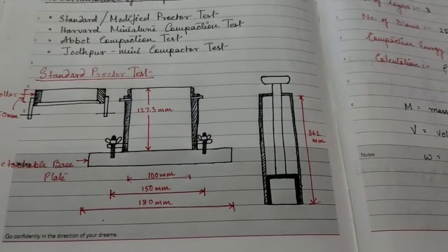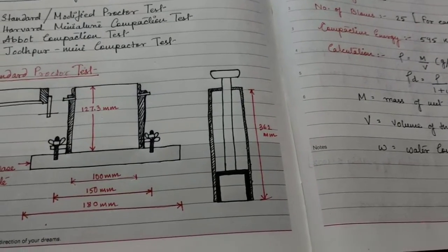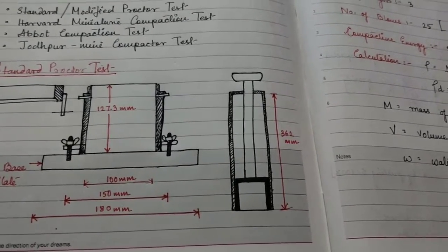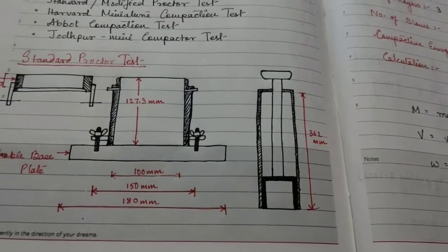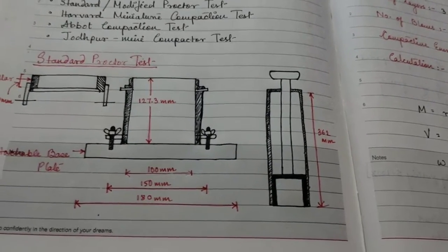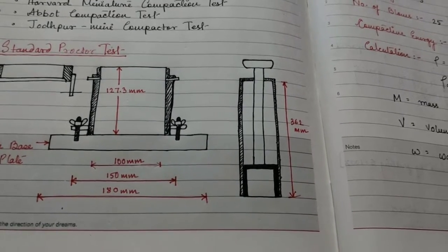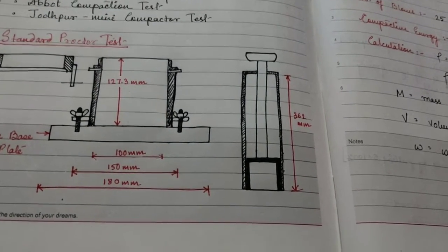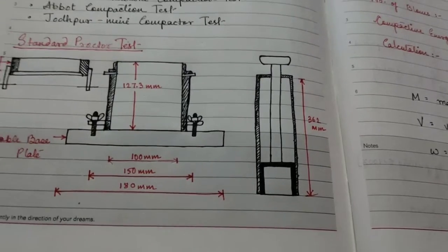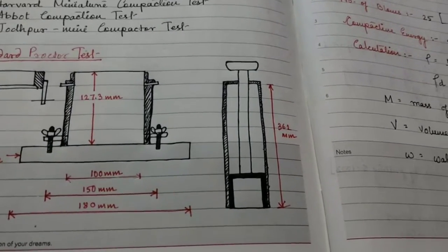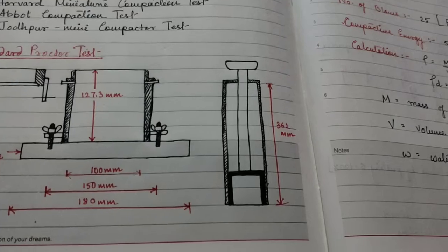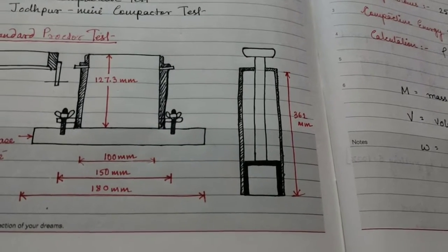These are different for different kinds of soils, and this maturing time is mainly permitted for proper water absorption. The initial water content that can be mixed with the soil may be taken as 4% for coarse grained soil and 10% for fine grained soil.